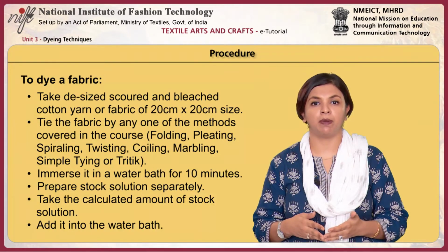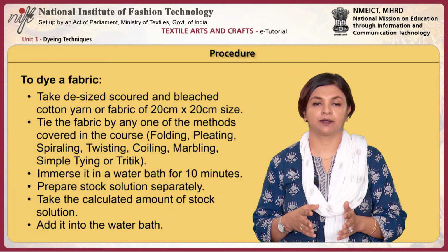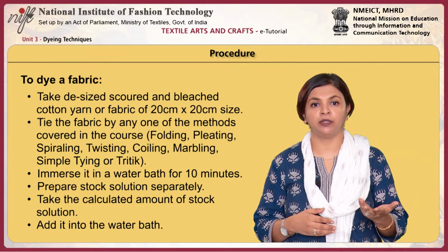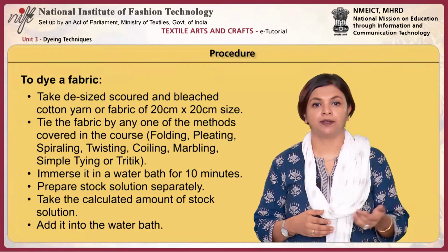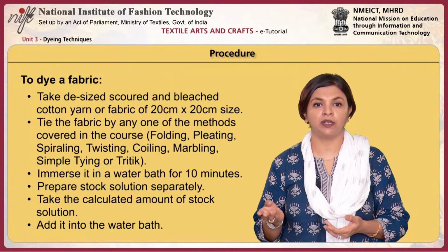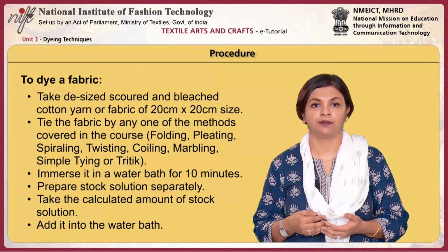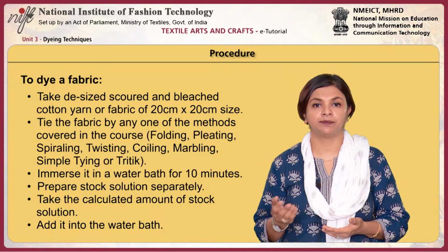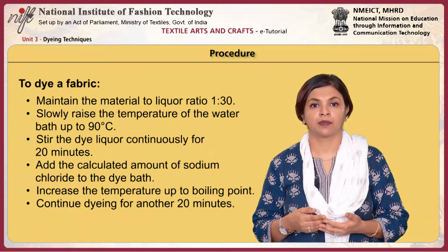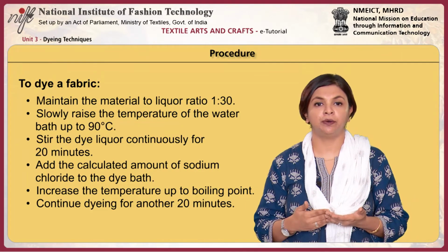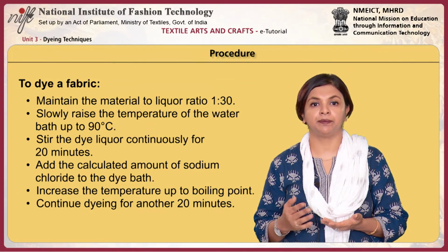Immerse it in a water bath for 10 minutes. Prepare the stock solution separately. Take the calculated amount of stock solution. Add it into the water bath. Maintain the material to liquor ratio at 1:30.